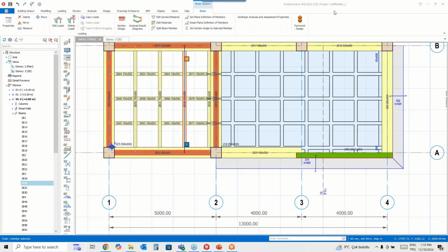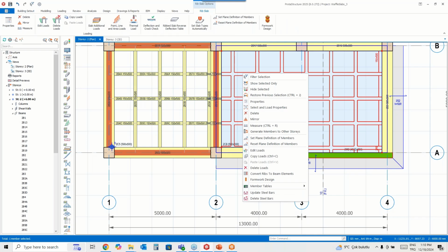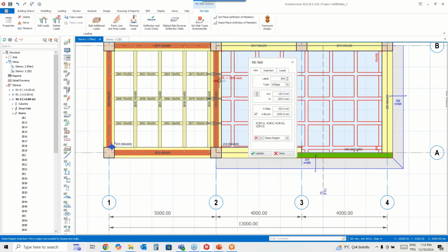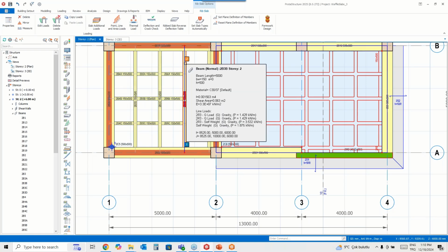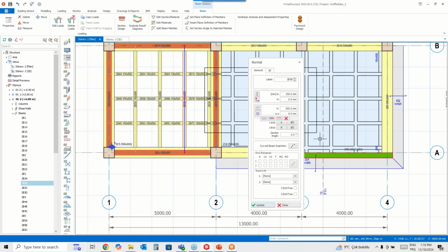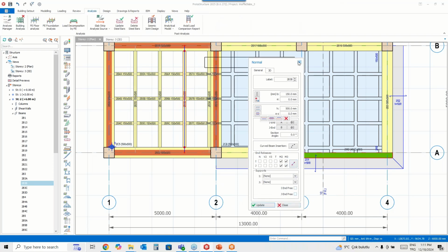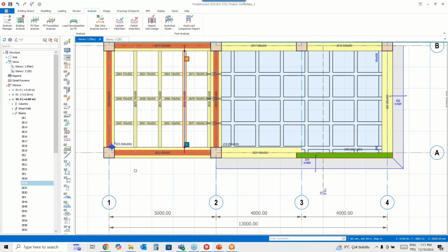So, what you can do is, as I know, in precast systems they just hinge both ends, so you can use this prefabricated option, or you can simply transform to real beams and add these hinges manually from here. Then you can review the detailed report that we are providing with the deflection results.